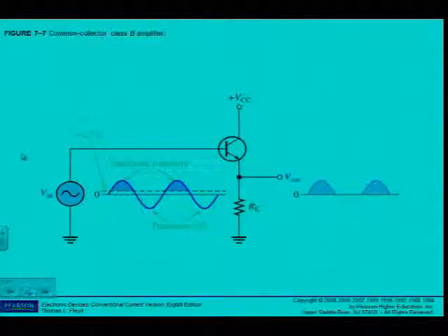There I can see, can you see there's no biasing? There's no VBB, there's no voltage divider, nothing. No biasing is done on a class B amplifier. Only the signal that is applied, the input signal. So the input signal is applied, what happens? VBE must reach 0.7 first, right? Then it conducts that portion, and when it goes below approximately 0.7 again, it switches off.